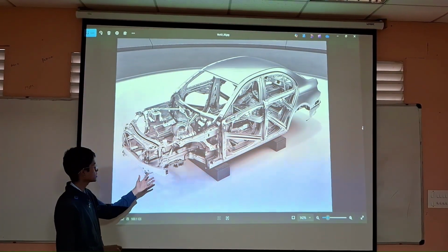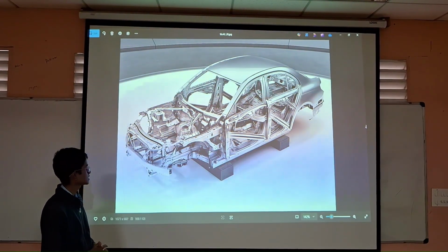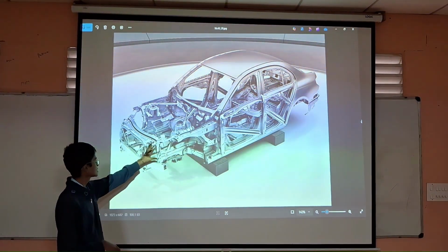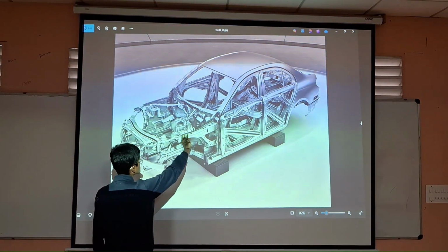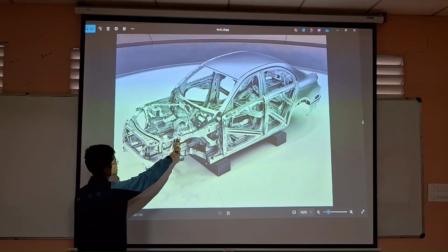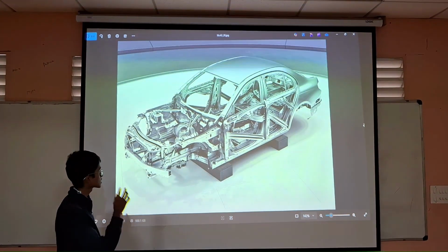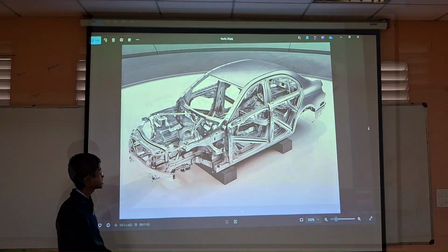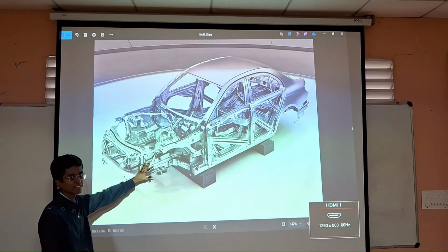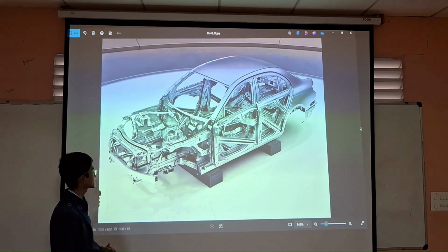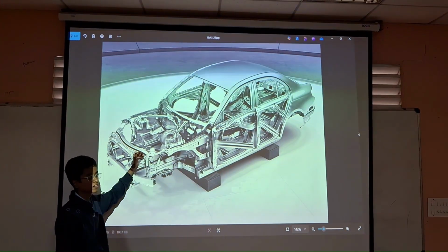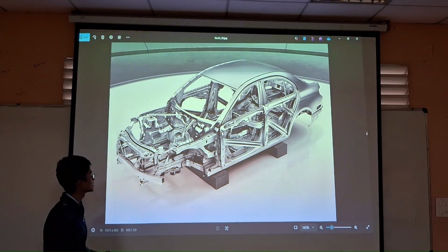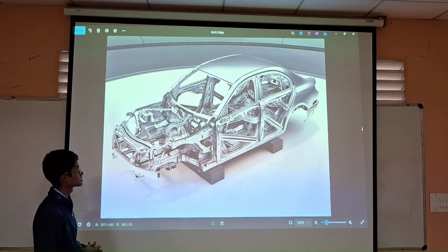It carries the hard points on which the suspension and wheels can be fitted and assembled. Separately, it has a firewall which, if any accident occurs, prevents intrusion into the cabin, and it has an engine cradle system on which the engine can be mounted. It has separate cradle mounts so the engine can be mounted longitudinally or laterally to accommodate its specific engine size.